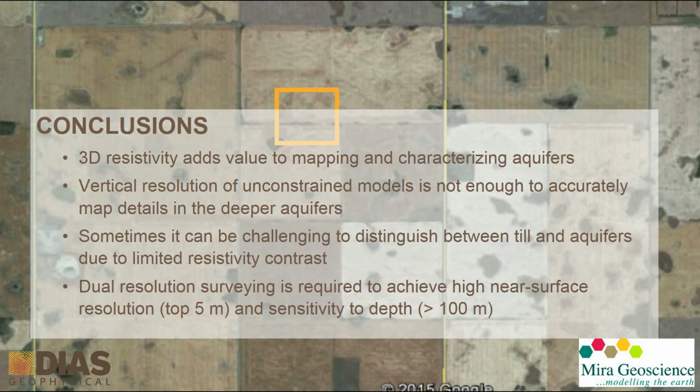I think it's really important to understand how 3D a 3D survey is. And if you don't have current flowing in all directions, you don't really have a 3D survey. So you look at an offset 2D survey. If your electrodes are all running along a couple of lines, you have very, very little 3D information. So I think the rose diagram is a very good way of depicting that, particularly to geologists who understand those types of diagrams, and it can help us as well to understand how well we've designed our surveys for the purpose.